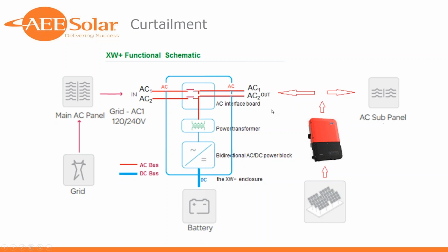And when this relay is closed and we've got power available, the PV inverter will, let me take a pause there because I think it's important to describe the goal in life of a PV inverter versus a charge controller. The goal in life, if you will, of a PV inverter is to harvest as much power as electrically possible from this array and dump it out onto whatever qualified grid it sees.